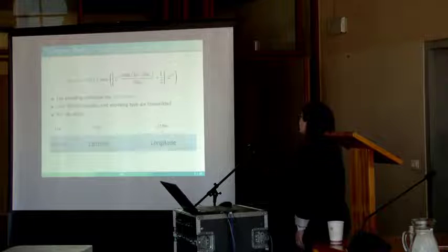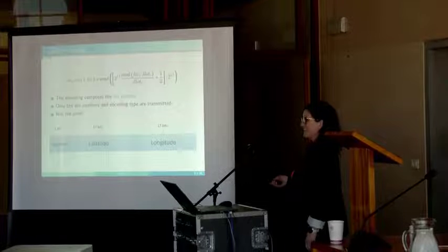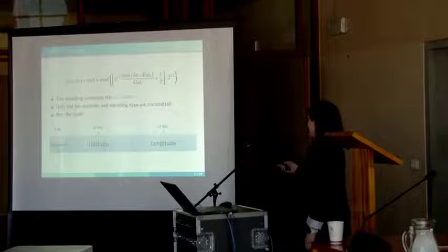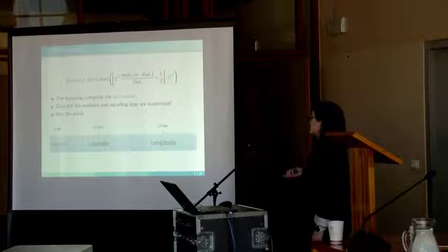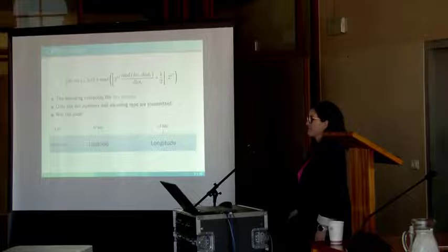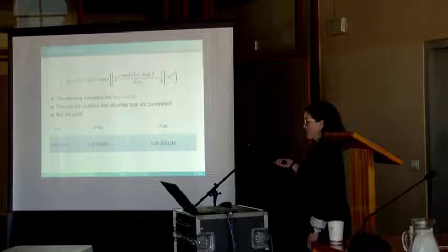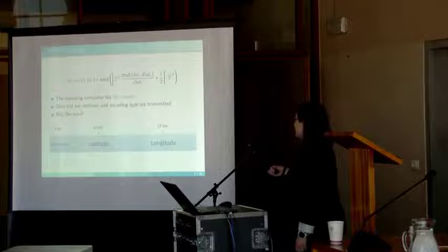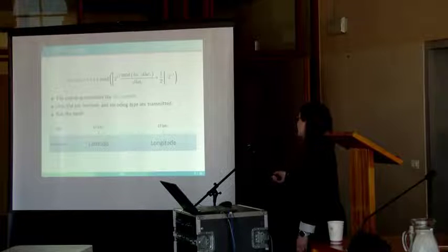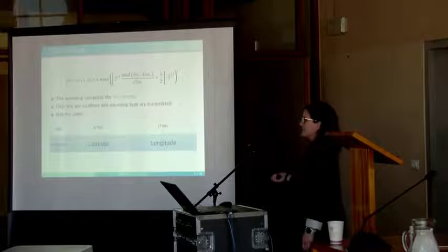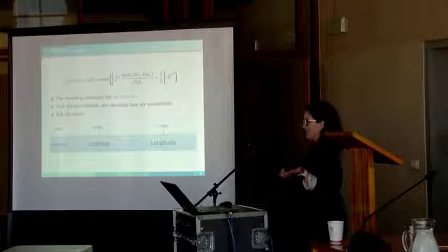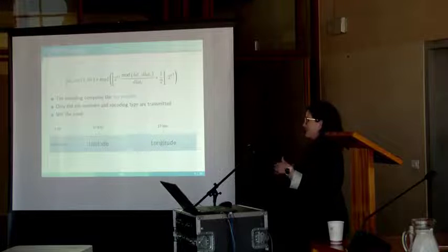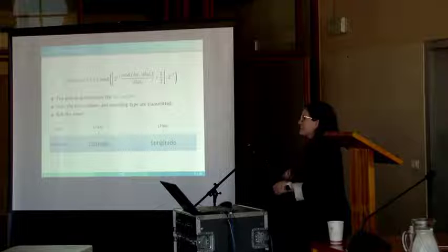So, the CPR encoding is actually very easy. It's this expression right here that computes the bin number. The interesting thing about CPR is that just the bin number is broadcast. So you have 17 bits for the latitude, 17 bits for the longitude, and 1 bit that says whether your encoding was an odd or an even encoding. You just have the bin number, you don't know in which zone it is. So yeah, that's not very useful.